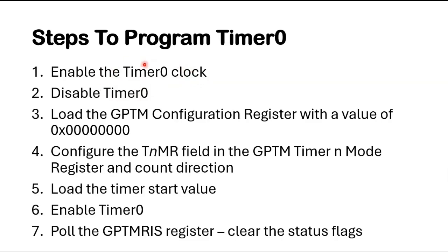I'm using timer 0, so that's why it's timer 0. Second step, disable timer 0. Third step, load the GPTM configuration register with a value of hex 0x00000000.